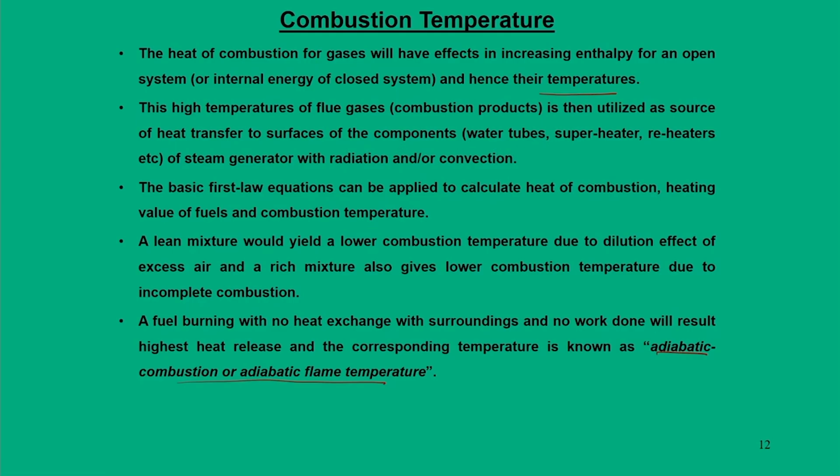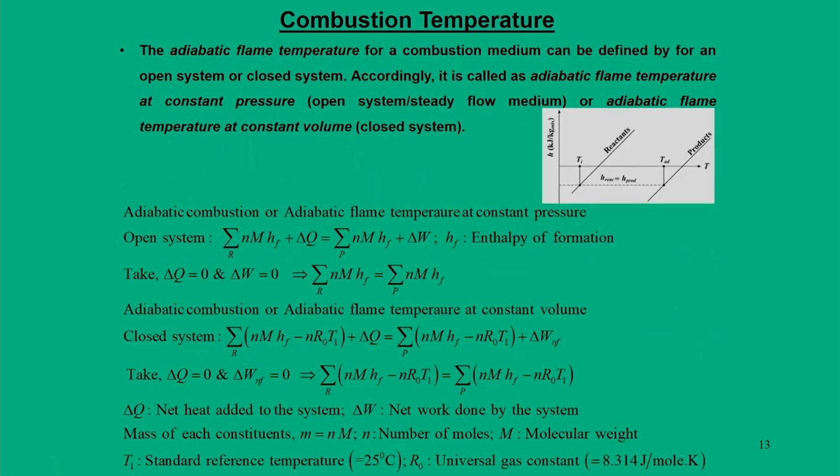So, to design such components, we need an estimate of the upper limit of temperatures that the component has to face from the flue gases. For this reason, it is essential to define this upper limit of temperature, and we call this the adiabatic combustion or adiabatic flame temperature.